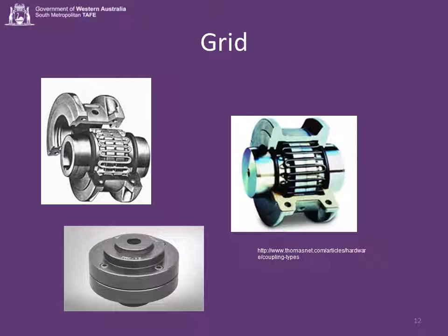They combine high power rating and high flexibility, like elastomers. Because it's 100% metallic parts, it is suitable for high ambient temperatures. The robust construction has no fast wearing components. The flexible grid springs are quickly replaced without disturbing connecting equipment. It protects against shaft misalignment. It sustains and reduces the vibration while transmitting the power.